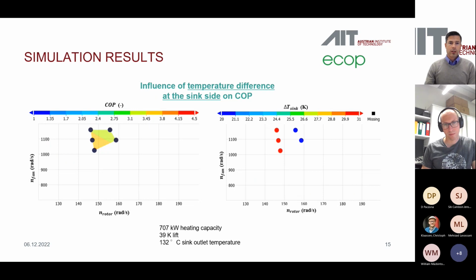So these are our tendencies that we found for the rotation heat pump, which were not, let's say, too intuitive. So we did not know about these, and it was not so clear to see such a sharp edge and the form then of the edge. What is a possible and allowed operation range of our two influencing variables, because we just have them two. It's only these rotor and fan speeds that we can really influence. The rest is given sort of boundary conditions or has to be reached in, for example, the outlet temperature.